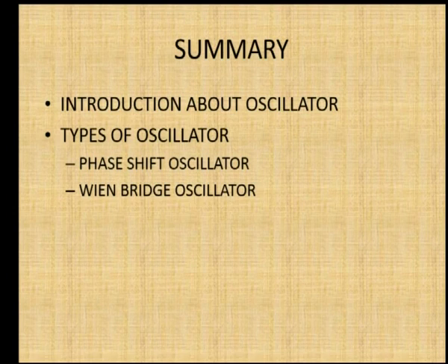We are going to see all the types of oscillators, and the classification of oscillators is based on the types of passive components used. You can use L and C, you can use R and C. You can use a bridge circuit, the Wien bridge circuit, in the feedback network. So, according to the types of passive components used in the oscillator and according to the range of frequencies generated, they are named as Wien bridge oscillator, RC phase shift oscillator, Colpitt's oscillator, Hartley oscillator, and so on. In the remaining sessions, we are going to see the remaining types of oscillators.